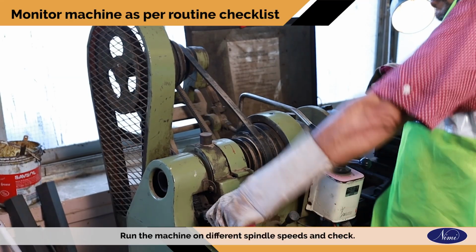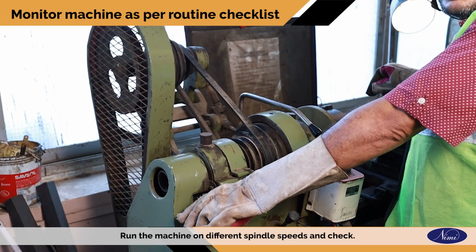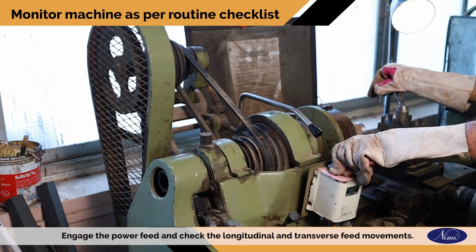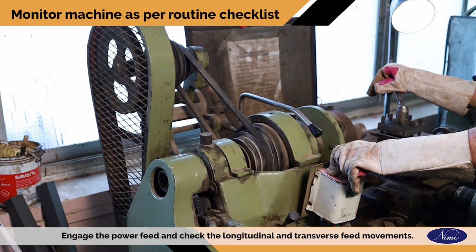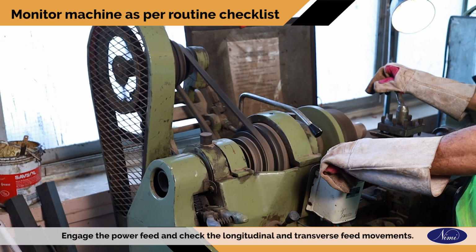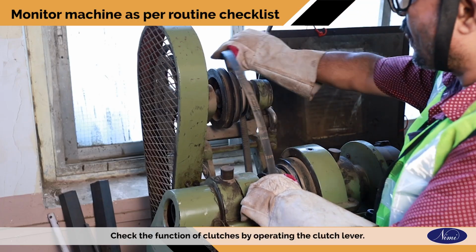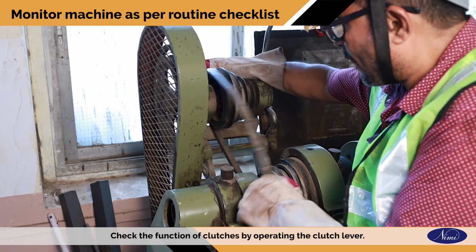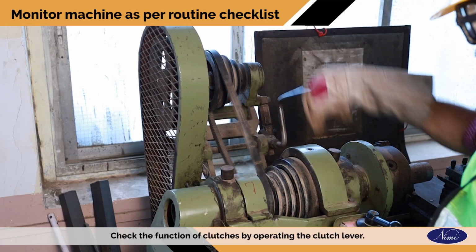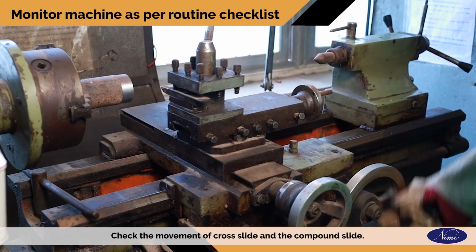Run the machine on different spindle speeds and check. Engage the power feed and check the longitudinal and transverse feed movements. Check the function of clutches by operating the clutch lever. Check the movement of cross slide and the compound slide.